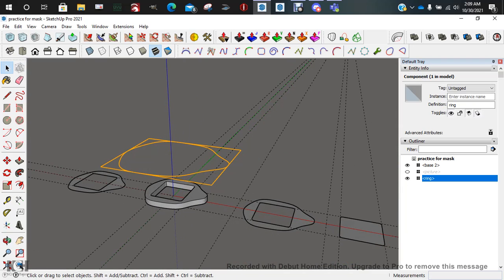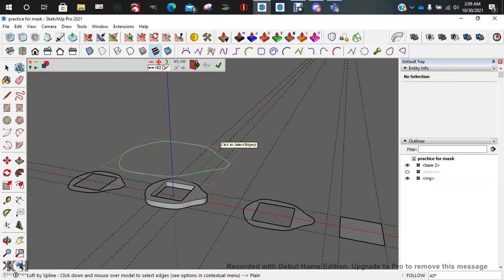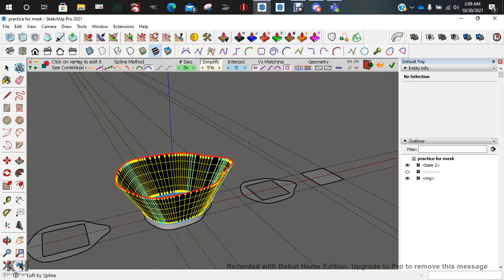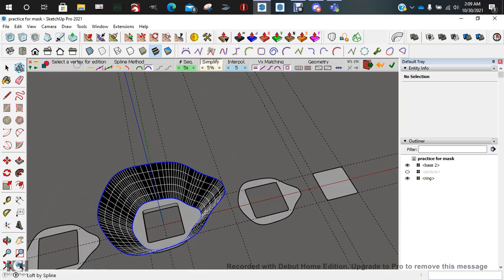You can explode the curve and explode things, and then select not the curve, explode the components, select the curves first, and then hit Curvy Loft. But it doesn't matter. So I'm going to click this, click that, click OK. Okay, great. Now we kind of have a profile that we like.